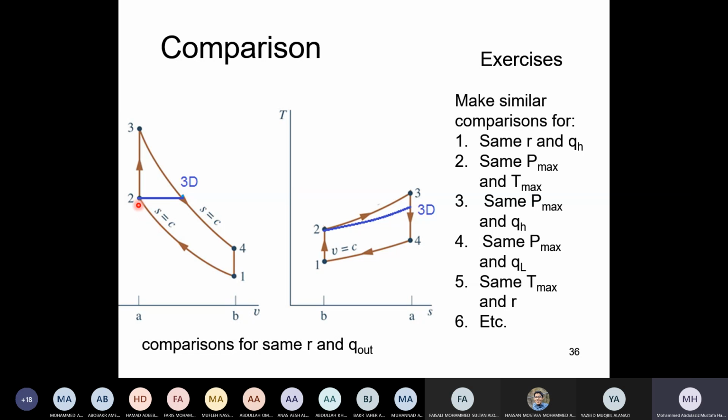What do I have here from 1 to 2, air or air and fuel? Air only. And can I heat this up to the self-ignition temperature? So now we reach state 2 higher than the self-ignition temperature. Will it burn or not? How come? You have only air. No, it will not burn because there is no fuel, right?